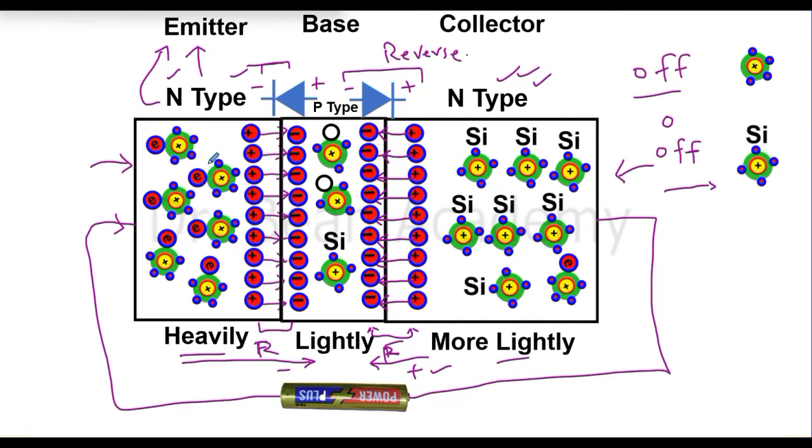That's why I will call them emitter n-type and collector n-type, or just collector and emitter, because n-type will help us understand what the terminal is and what the atoms are. So remember that merely exchanging the terminals of a transistor is not identical and it is not advisable. You must be careful when connecting a transistor in your circuit, about where the emitter is and where the collector is.